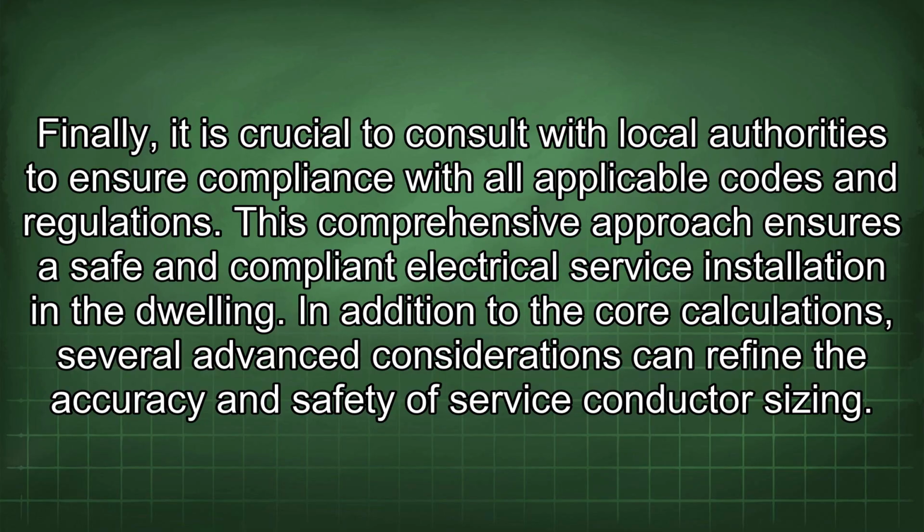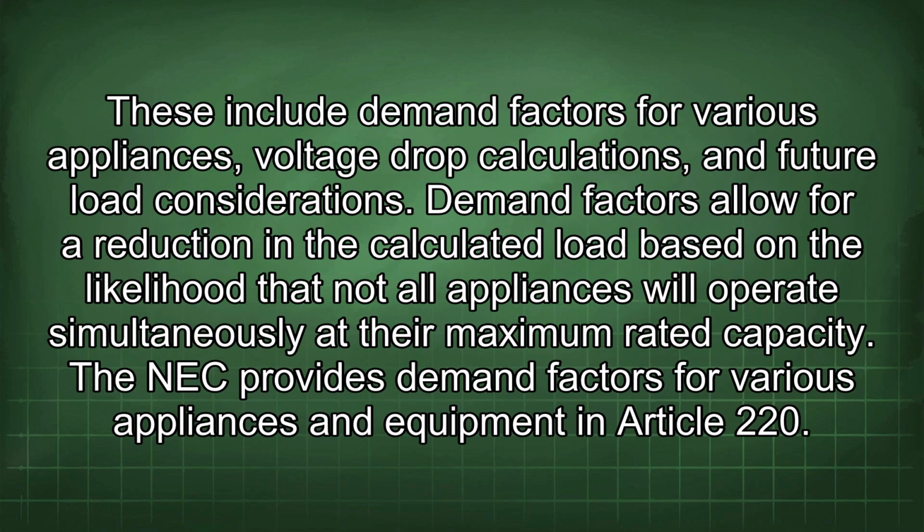In addition to the core calculations, several advanced considerations can refine the accuracy and safety of service conductor sizing. These include demand factors for various appliances, voltage drop calculations, and future load considerations. Demand factors allow for a reduction in the calculated load based on the likelihood that not all appliances will operate simultaneously at their maximum rated capacity.